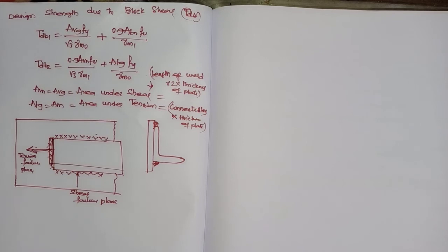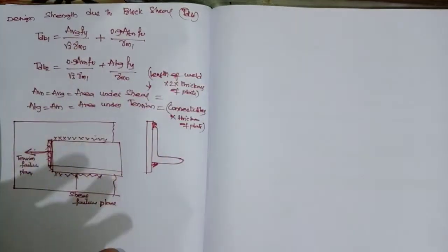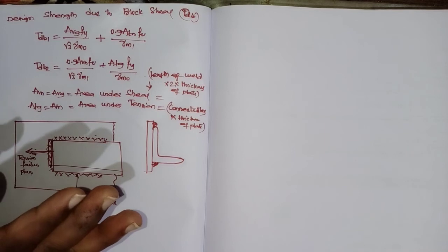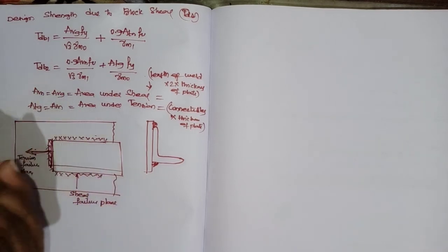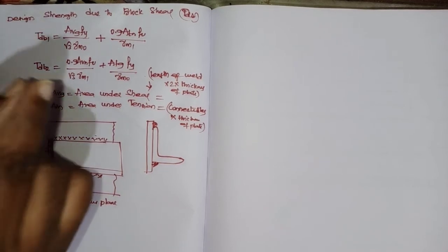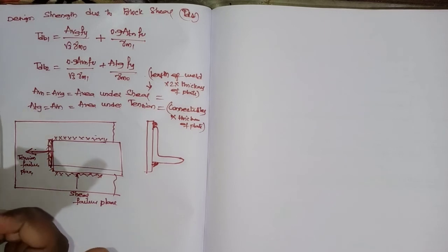A tension member connected with a welded joint will be more effective in taking the loads. A tension member made with welded joints will take more load, means more effective than bolted and riveted, because in a welded joint we are not deducting anything for bolts or rivets. Gross area equals net area.